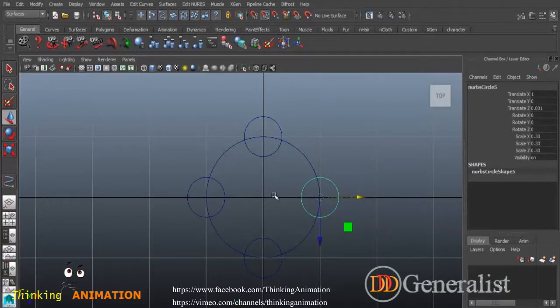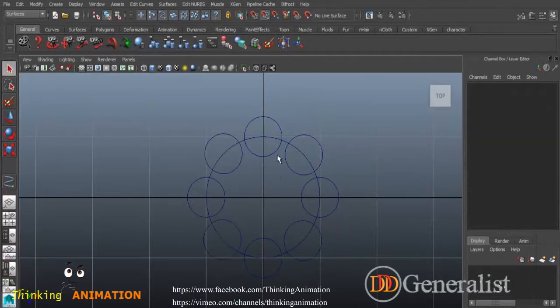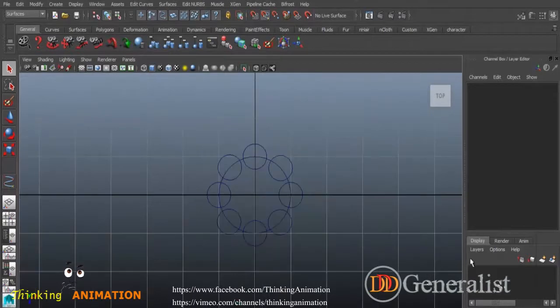And if you want to snap to other points, you select here, Ctrl D, duplicate this, use the move tool, and click right onto this box, meaning I'm going to select X and Z both. If you want to bring it right here, you can Ctrl D, bring it right here, Ctrl D, and now with the middle mouse button press, click here, and you get it here. You know how to snap with the middle mouse button press, and just nudging your mouse around, you can snap your objects to any curve or line.